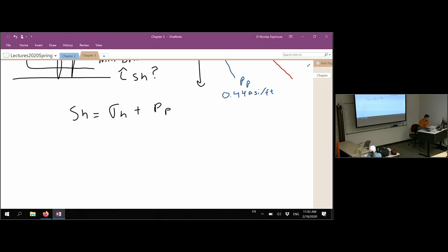On the right hand side, that one is effective. Okay, but I already got the equation for this effective horizontal stress. If I assume linear elasticity and an isotropic solid, it is going to be this, right? But I already have an equation also for effective vertical stress, which is the total vertical stress, something I know how to calculate, minus pore pressure.